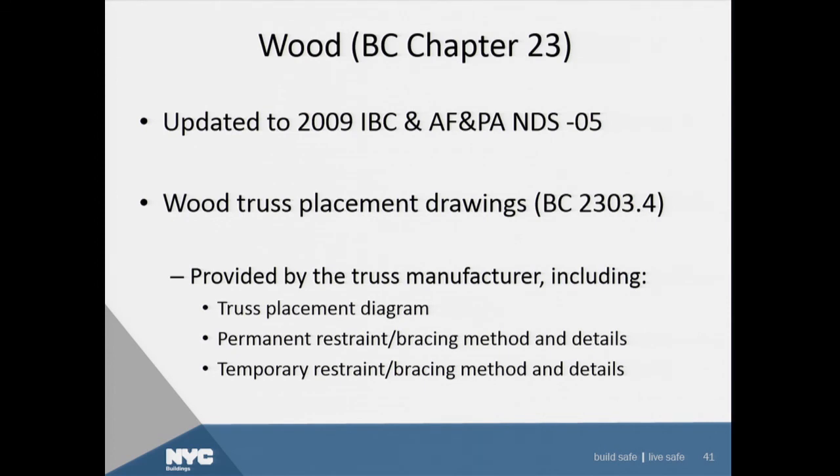And last but definitely not least, wood. We've updated to the 2009 IBC and the 2005 edition of the reference standards there, and they are similar to the steel joist placement plans. You have requirements for wood truss drawings and wood truss placement plans that must be maintained on site and provided by the manufacturer.